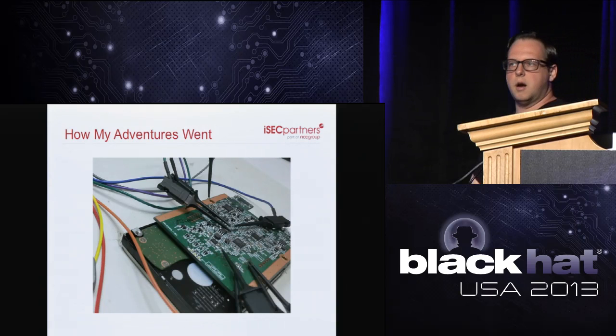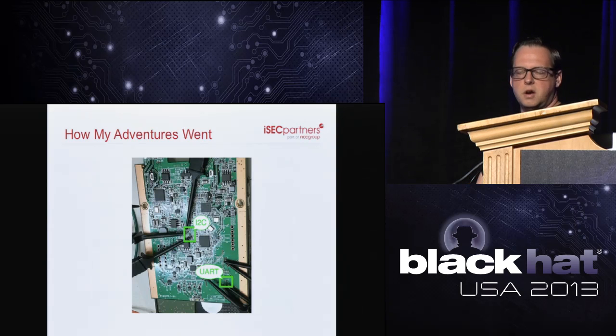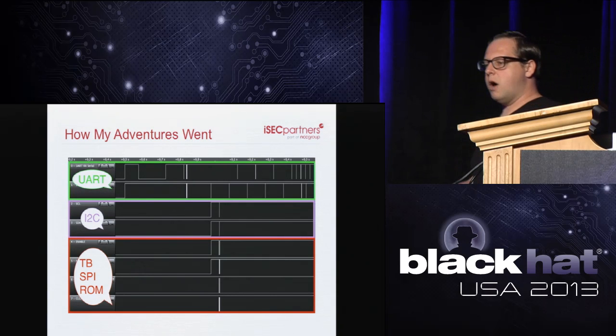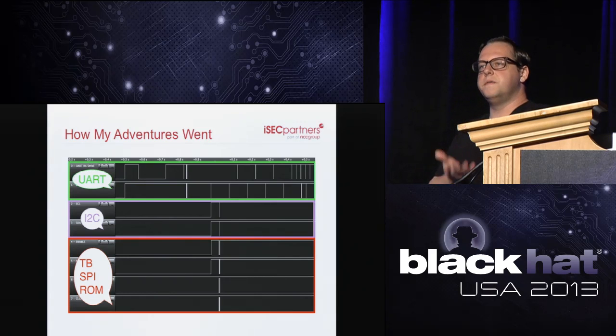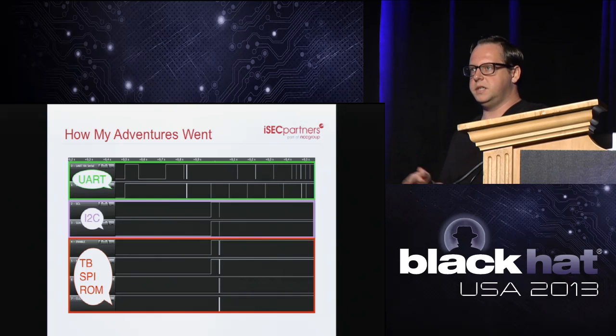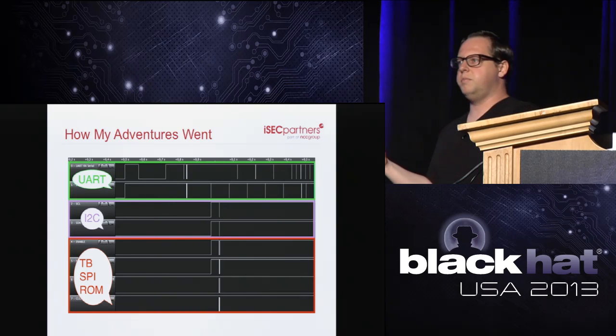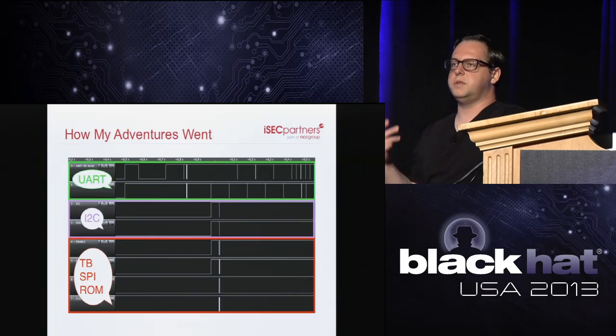Once our wires are soldered in and our epoxy set up to protect it, we can start sniffing the board and sniffing all the traffic on there. Notice our I2C connection being sniffed, and also our UART connection at the bottom into our ARM Cortex from our Apple. So here's an image of the output of the logic analyzer, and it might be hard to see from this image, but basically the UART comes on first, and the UART transfers data. Even before Thunderbolt ever boots up, Thunderbolt isn't even hot yet. Once the ARM does its thing and gets programmed by the Apple, then Thunderbolt comes on. The I2C buses start communicating between the ARM Cortex and the Thunderbolt controller, and device information is now sent up to the computer through the Thunderbolt.